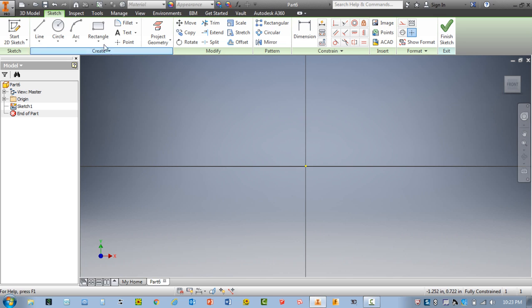Now you've seen me do a few demos where I'm using this rectangle tool. So we're going to go ahead and create a 2-point rectangle. Let's click once. But this time the approach is going to be a little bit different. I'm not going to draw what we've been drawing, which is the overall length and height. If you look carefully at Isocirc 2 on your paper, you'll notice there is a number in the front view that says 2.75. Let's go ahead and type in that 2.75 for the length. Let's hit your Tab key, and let's type in the height of 2.5.